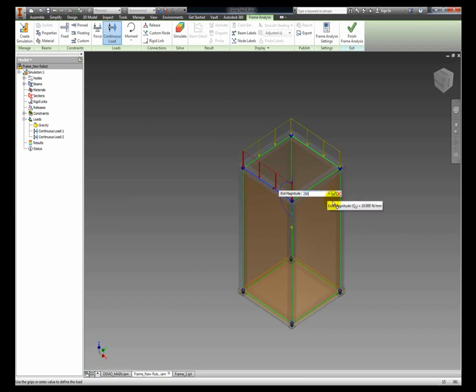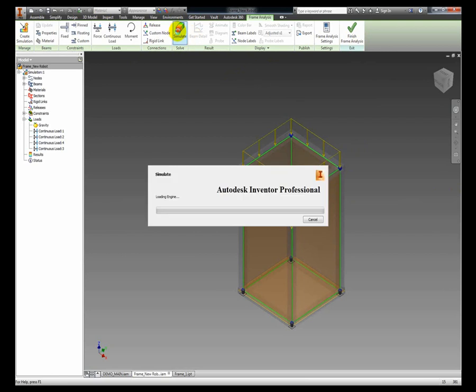So to check that these beams are correct. And that one's actually changed slightly, so I could go back, and the nice thing of this is just delete them if they're not there, and go back and put the correct one in. So I can put that as 250. So we've now created our simulation, got a rough idea, we just want to see if this is going to work. So I can hit solve.